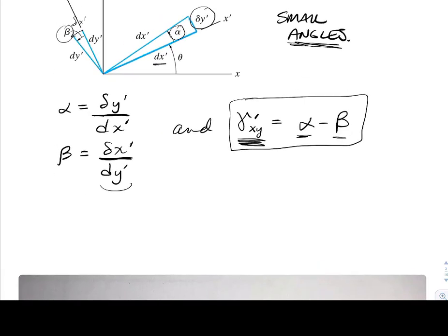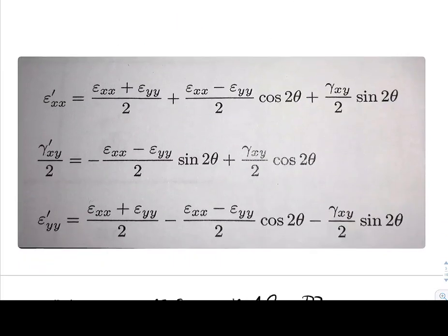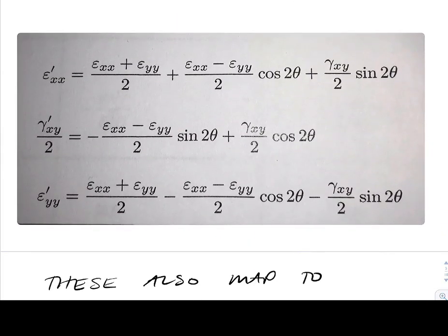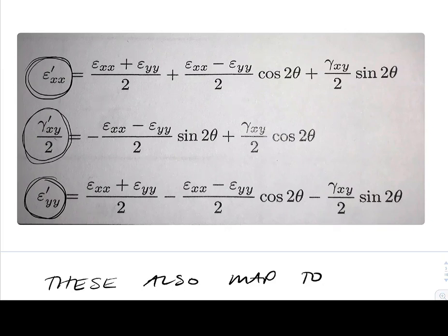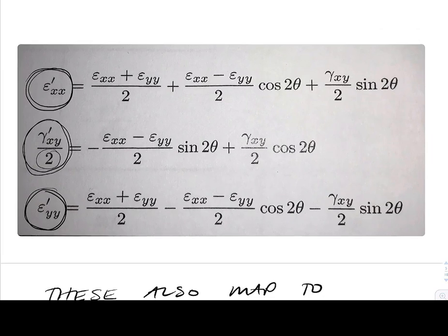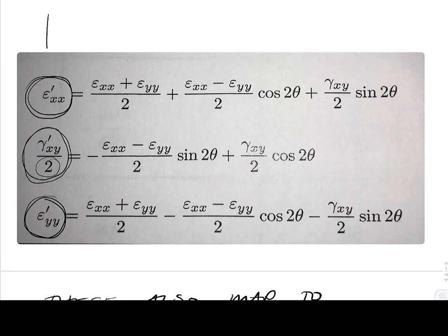So we got a little bit of math, again, to work through there. And we're just going to jump to the final equation. So this is right off your equation sheet. So you end up with an equation for normal strain on the x prime axis. You've got normal strain on the y prime axis, which is going to be perpendicular to the x prime. And then the shear strain, which works between. And you also see this gamma over 2 that shows up. So let's just look at the big picture here. What do we need here to calculate transformed strains? We need 3 initial strains.